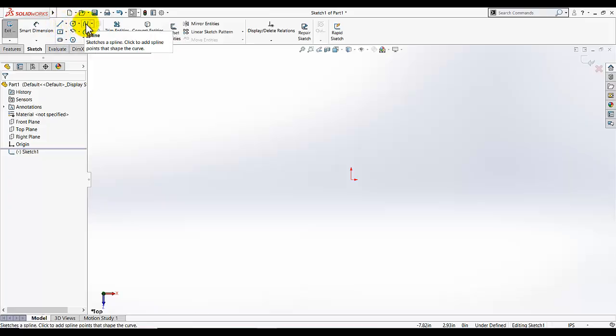If you are not familiar with SolidWorks and you are just going to start from this video, that's why I am going to explain some little steps for you. So I am going to design a rectangle. Just select this corner rectangle. There are different types of rectangles. The method to draw them is different, and for this design we can select the center rectangle, but I am going to select the corner rectangle and then make it in the center of the origin.